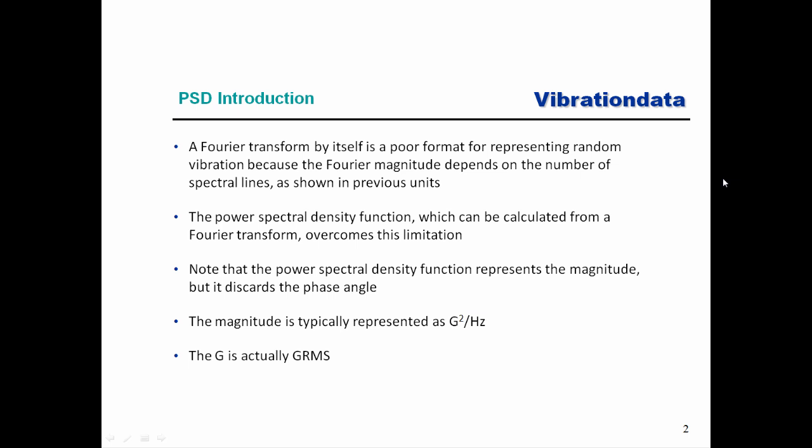And we typically would just cancel out of that plot and only look at magnitude for Fourier transforms. There are some cases within vibration testing where phase is important. For example, if we're doing modal testing, M-O-D-A-L, phase angles are important. And there are some other situations as well in which phase would be important.